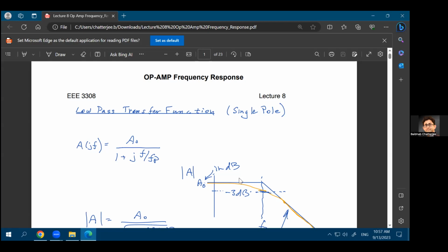So that's why you are calling this a pole frequency. All these equations will start to make sense if you go over it again, and it is provided in the handouts as well. But this is why we are calling this a pole frequency at 1 upon R naught C naught, where the power becomes half or the voltage becomes 1 upon root 2 times in the transfer function.